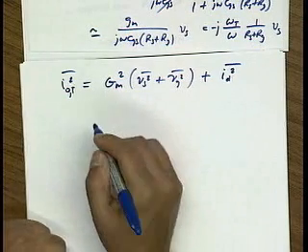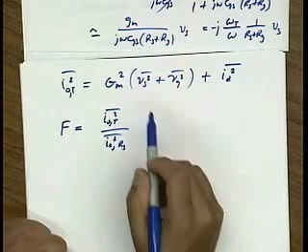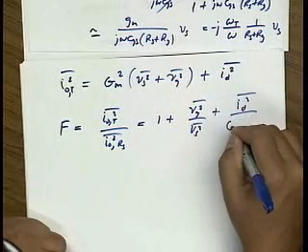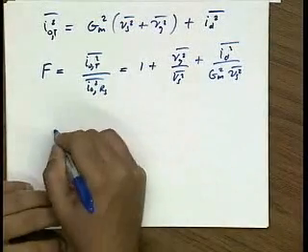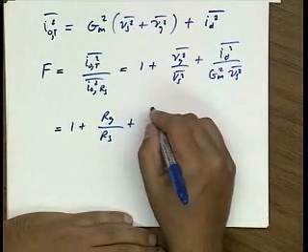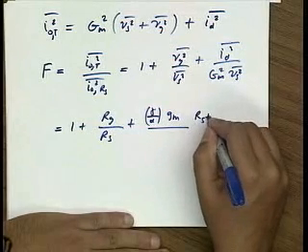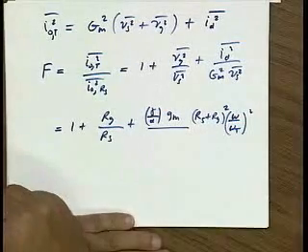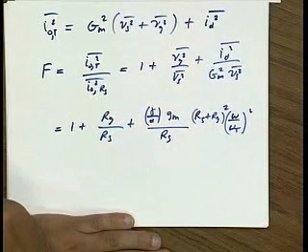Good. All right, so from this expression I can calculate the noise figure. The noise figure is the total drain current divided by the drain current just due to Rs, which is just this first term here. So that gives me 1 plus Vg squared over Vs squared plus I drain squared over Gm squared Vs squared. Okay. And just as before, we now substitute 4kTb Rg here, 4kTb Rs here. For the drain noise current, I substitute gamma over alpha gm. For Gm squared, I substitute basically Rs, 1 over Rs plus Rg, omega over omega t squared. I'm interested in the magnitude, so that goes away. And on the denominator, I have Rs. Okay. Any questions?